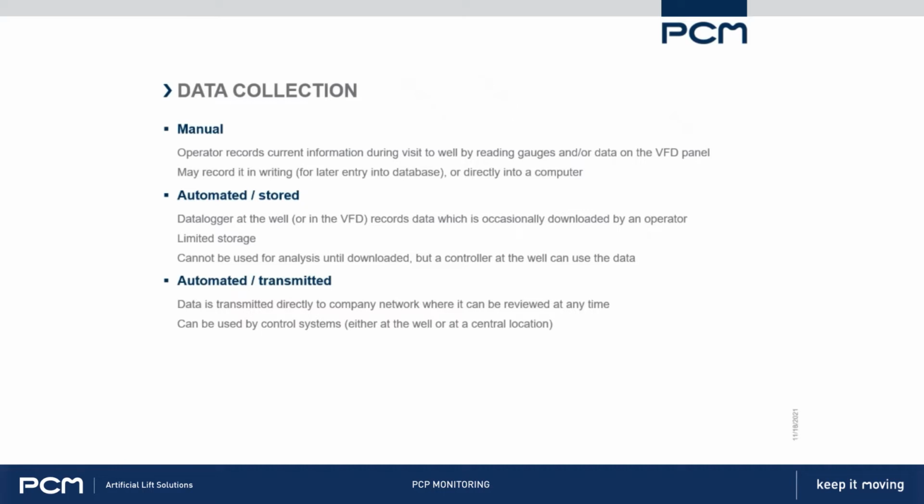Obviously, there's higher costs as you go down this list, but more advantages. If you do the local data loggers, there's a trade-off between how often you can store the data and how often you have to download the data back onto the network. Because if you're storing it every minute, for example, you might have to come out every couple of days to download that data because it'll fill up the local storage. But if you store a data point once a day, then maybe it can last a month before it has to be downloaded, depending on how much memory there is locally.